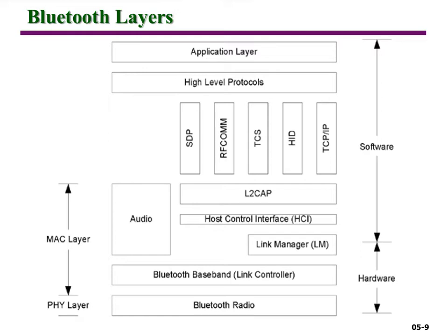So you can use a Bluetooth device as a mouse, right? In which case, you need to emulate communication similar to serial communication, right? So you can use a keyboard or a mouse. Keyboard or mouse uses serial communication, right? So Bluetooth provides RFCOMM, which is an emulation of serial communication over wireless. Okay? Or you can use a human interface device. For other human interface devices, you can use Bluetooth, like EEG headsets or something like this.